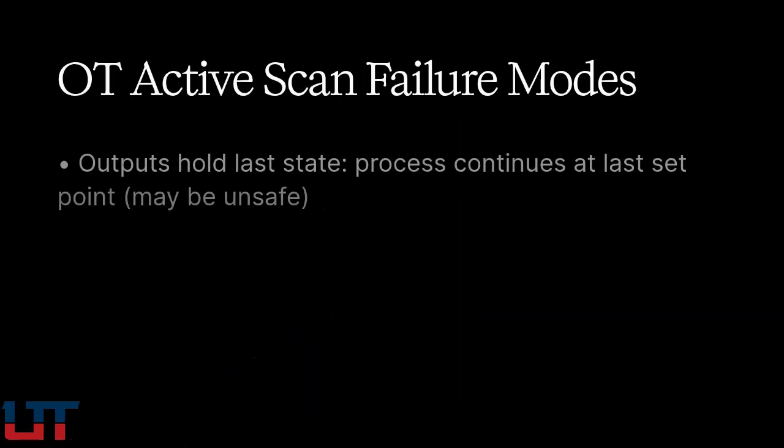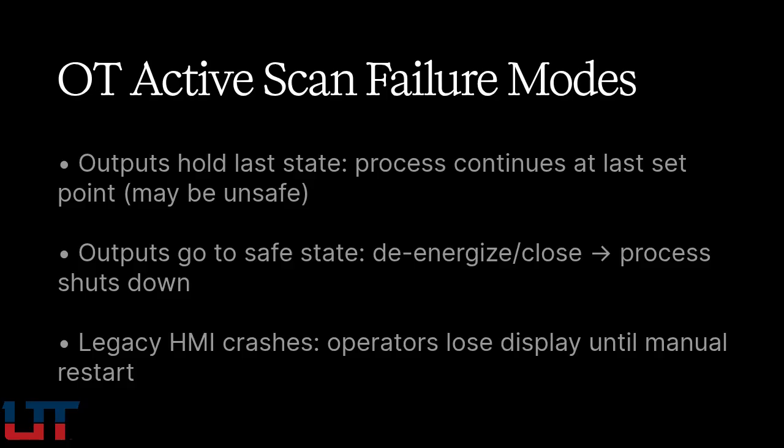The failure modes from aggressive active scanning in OT environments span a range of severity. Again, a PLC faults and its program halts. The immediate effect depends on that PLC's fail-safe configuration. If outputs are configured to hold the last state, the process continues at its last set point, which may be fine for a few minutes or may be dangerous depending on the process. If outputs are configured to go to a safe state, typically de-energized or closed, the process shuts down.